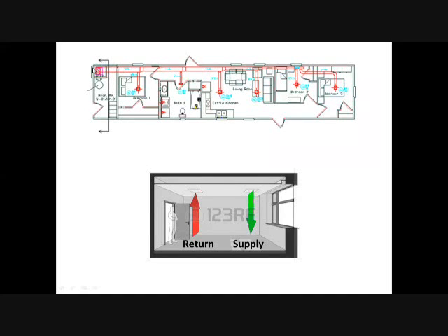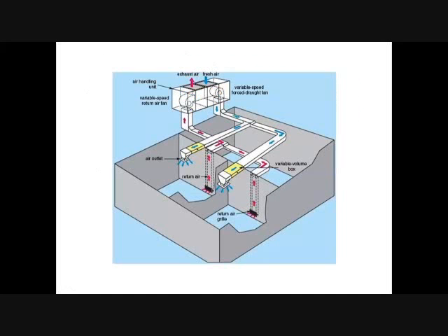So as you see in the diagram above, there is a duct coming from a vertical duct. So there is a vertical duct that brings the air from the chillers and returns the used air back again. And then there are supply diffusers in different places where it gives air to the different areas. Of course, some systems have the return, which reduces the cost. Some systems just let the air go out by the difference in pressure.